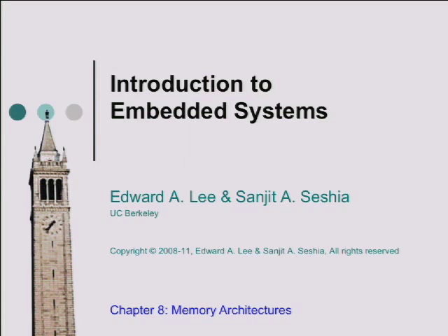The iPhone and Windows and Mac and Linux go to great lengths to hide from you a lot of what's going on in the hardware. And when you're doing embedded system design, you really need to understand what the hardware is doing, okay? A microprocessor is executing a bunch of instructions. What does it mean to do a context switch? How is it using memory? How is it going to behave when it runs out of memory? These kinds of things become essential in embedded system design.